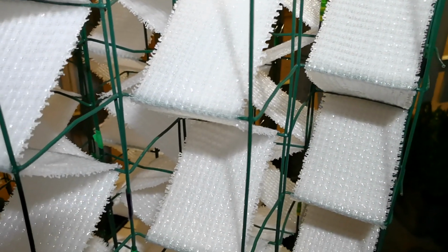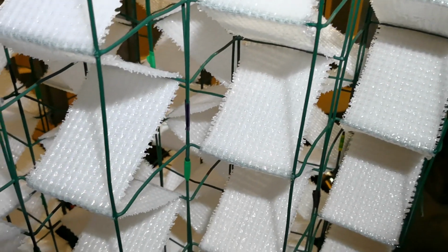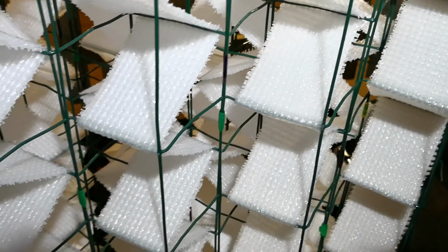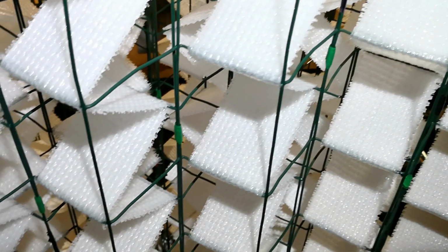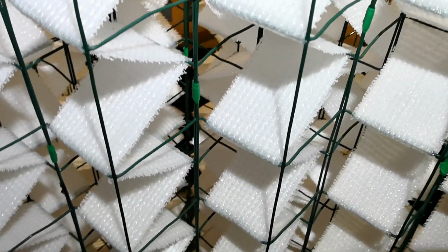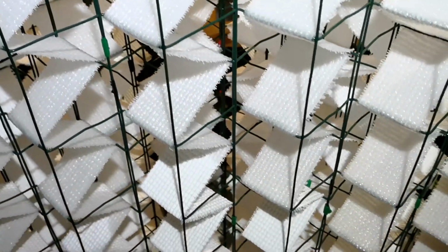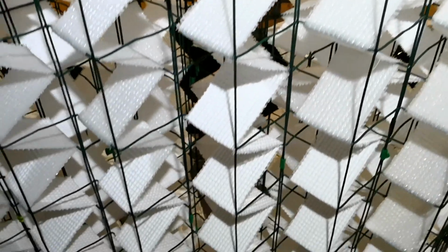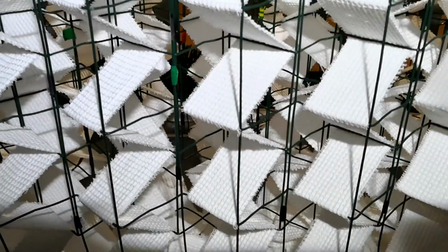The glycerol flows down the cotton stripes by gravity and gradually absorbs the humidity from the air. The energy source for the absorption is the water vapor pressure gradient between ambient air and dehydrated glycerol. The water molecules move from the zone of higher vapor pressure to the zone of lower vapor pressure.